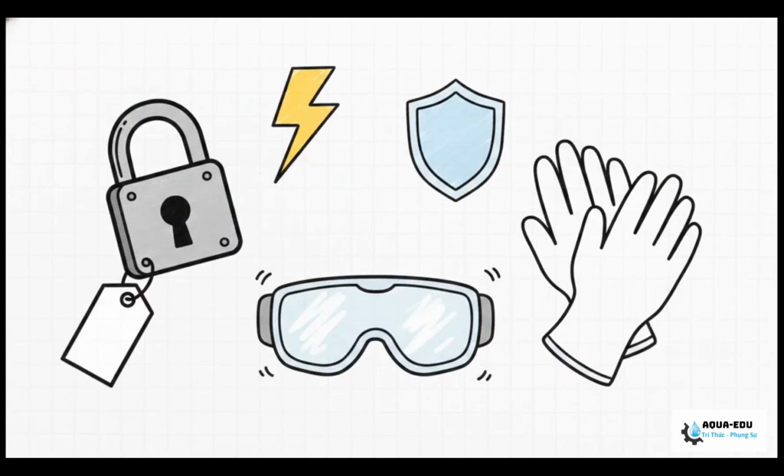I'm going to leave you with one final critical warning. We are dealing with high-voltage ballasts and dangerous UVC radiation out there. Your life and your health always come before the equipment, no exceptions. Follow strict lockout/tagout procedures, wear your UV protective goggles, and use clean gloves. Equip yourselves with this knowledge, stay safe out there on the floor, and let's keep our discharge crystal clear. So, I have to ask, the next time those lights go dim on your shift, are you ready to handle Incident 23?